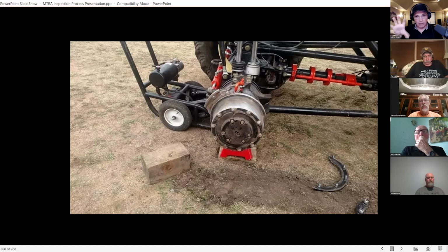Sometimes they're tight, but not centered, so as soon as the truck moves, the wheel moves just a little bit and now it's loose. Because these wheels use a taper, if it's off center, the wheel will tighten up against one side of the hole, not the full circumference of the hole. So it's very important to take their time to get the wheel properly centered.